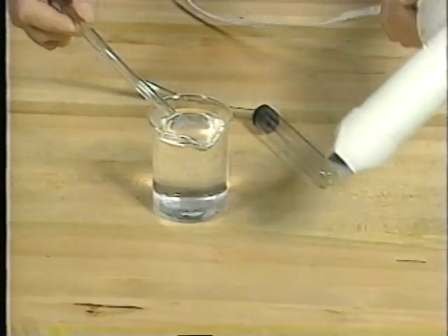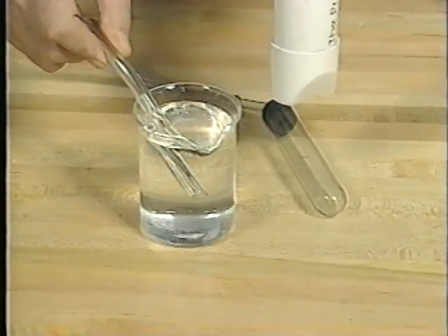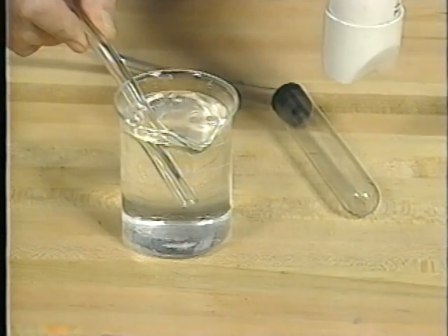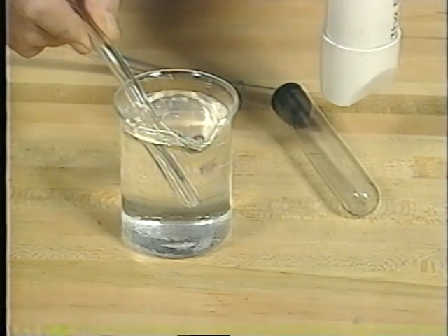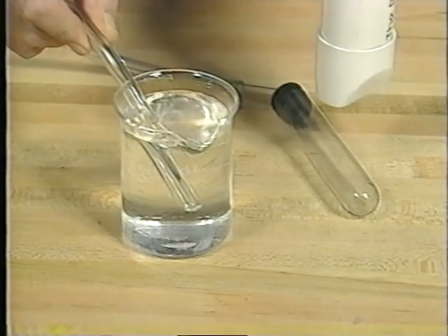While we were gathering information for this story, we talked with some engineers at Delphi E. They told us that the oxygen inside the sensor is there from when it's manufactured, and that the housing of the sensor is sealed, so you'd think nothing could get in or out. This setup demonstrates that air expands when it gets hot, which happens inside the O2 sensor every time the engine is run. So the sensor breathes through the wires.